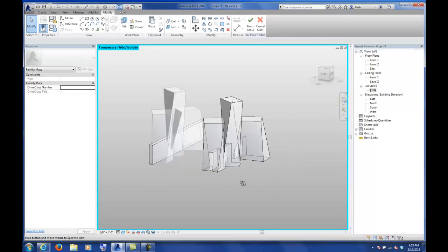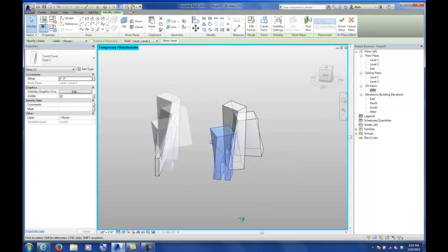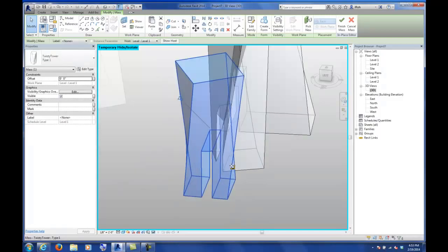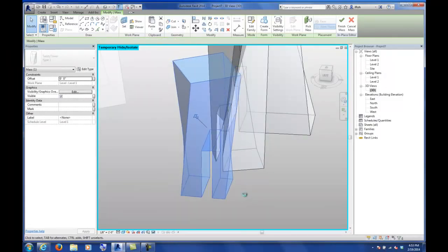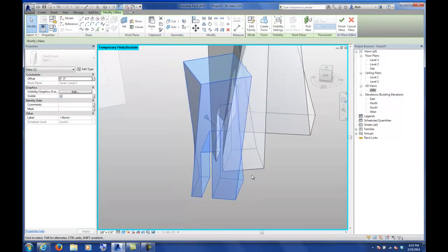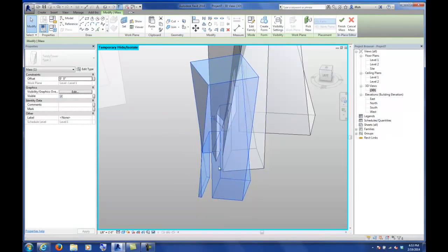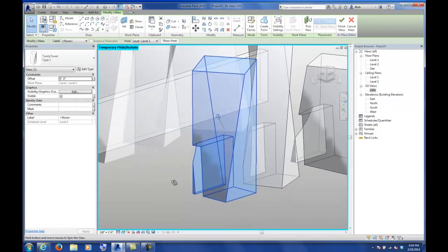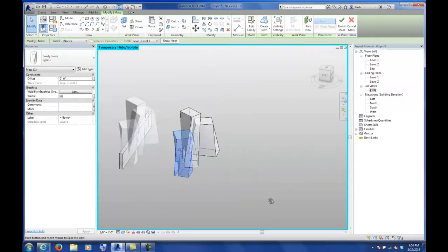And you can now see that if I were to take this tower and move it, it's always going to be based on wherever that other form was. So what's nice is you could actually also have the same tower, but depending on where it falls within this particular new extrusion, you could start to cut out additional edits to it as needed.